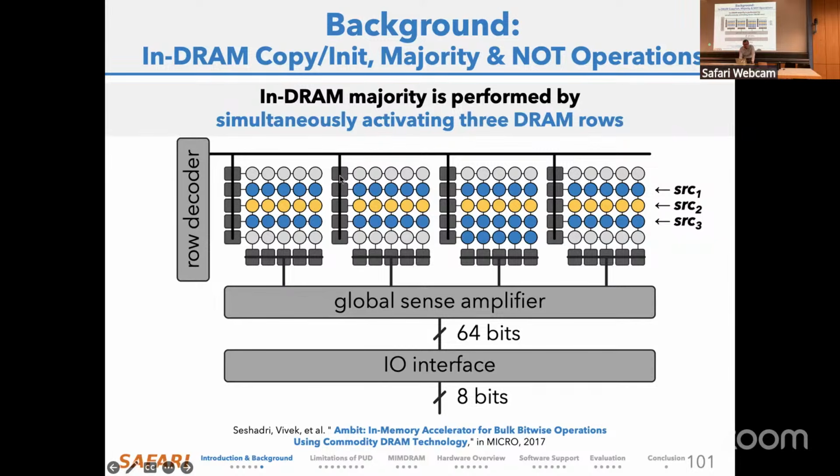And then there's another piece that's connected. There's a repeater over here to amplify the signal so that you can maintain signal integrity in this huge word line. Essentially, there are repeaters over here that amplify the signal to smaller sets of mats.